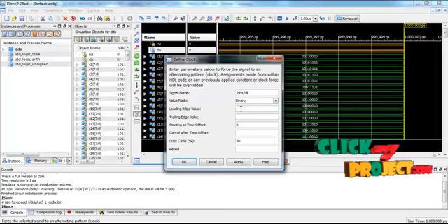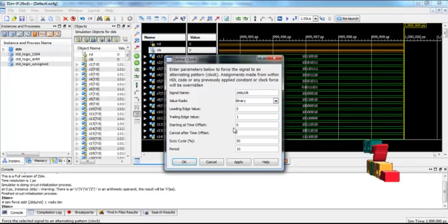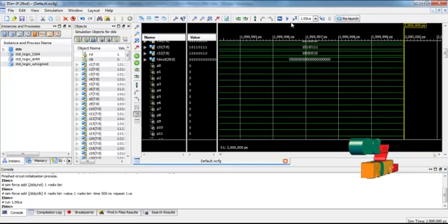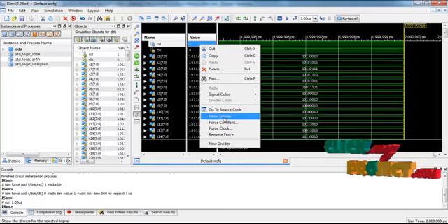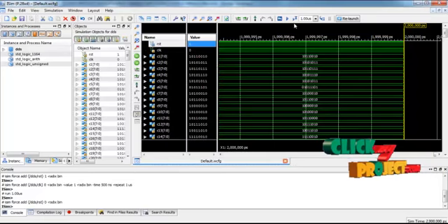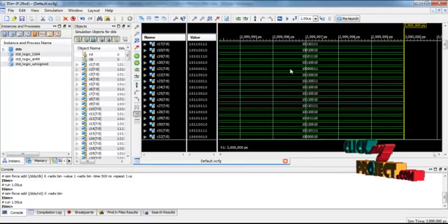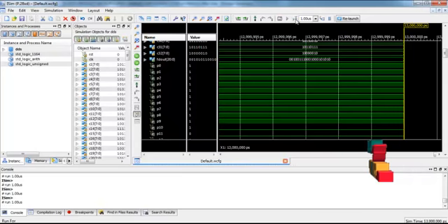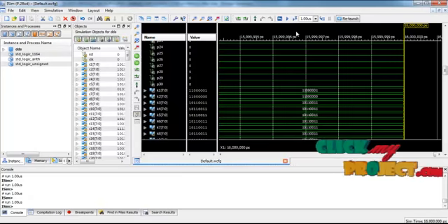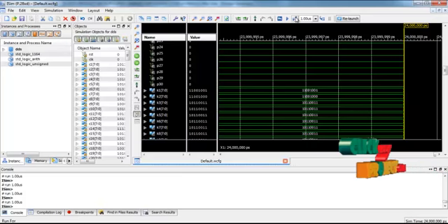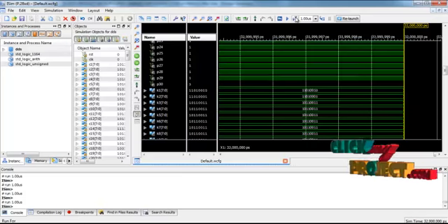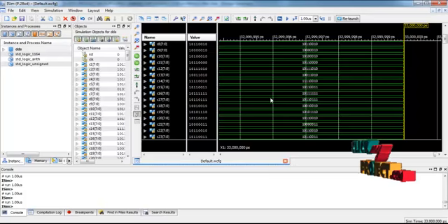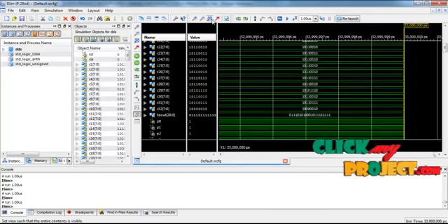Then remove the reset signal and pass the data shifting operation for the overall 32 tap FIR filter architecture. Then update every clocking signal for enabling purposes and pass the overall shifting operation to complete the 32 tap FIR filter architecture, and finally we get the final output for the overall FIR filter functions.